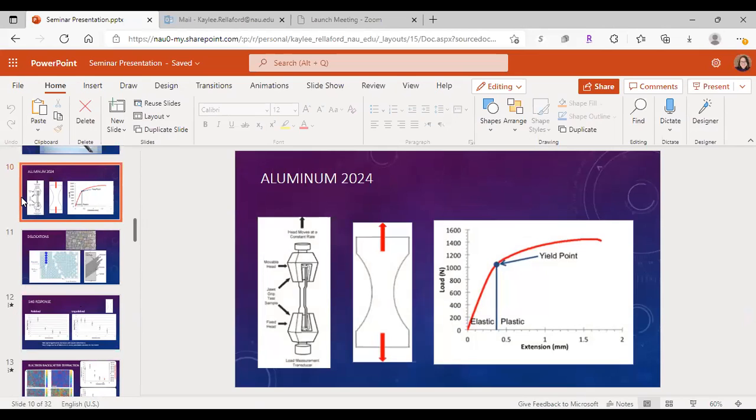Like you said, different loading might respond differently, even different surface finishings. We looked at unpolished and polished, but there could be different coatings, and optical SHG can look through paint. There have been studies where it looks through paint and gets a response, so coatings wouldn't be a problem, but that's one of the things they would need to look into. We didn't do any different type of loading.